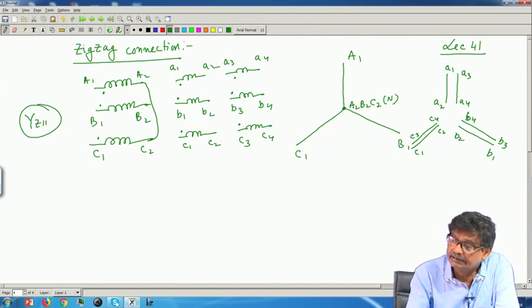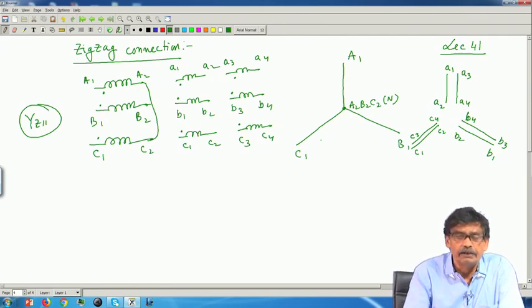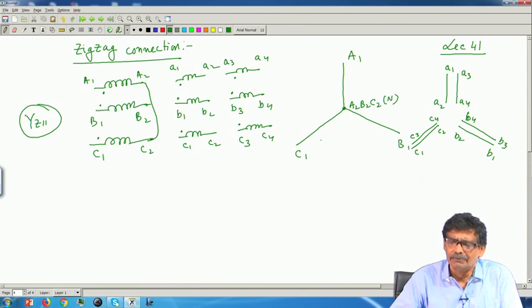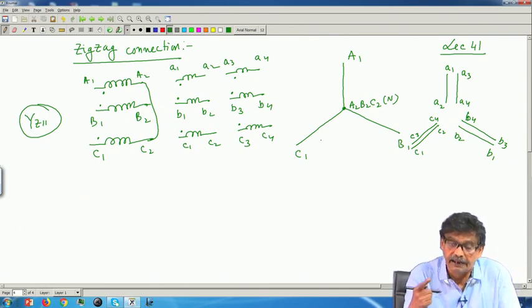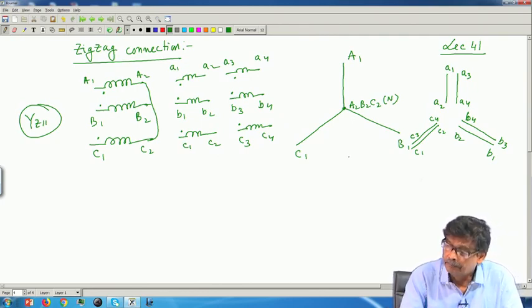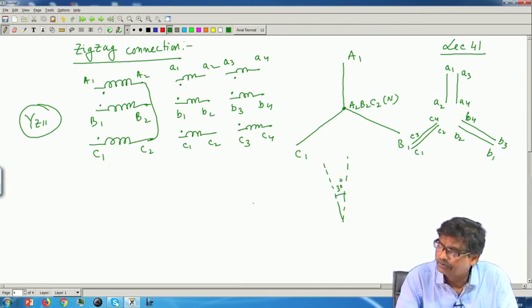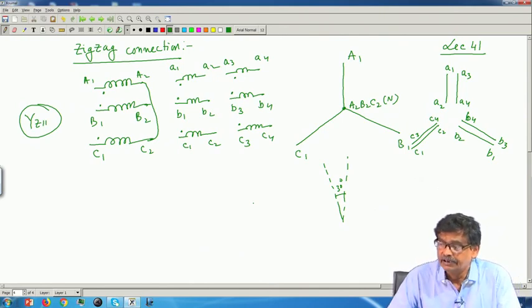Now, this is the primary voltage; whether 11 is possible. Zigzag connection, I know 3 terminals will be shorted. So, there will be a neutral point available, looks like a star connection. Therefore, whatever will be the phase voltage starting from that neutral of the secondary side, that A phase voltage must lead this A phase voltage. Therefore, I draw first this A phase voltage, that is at 12, and then I am expecting my phasor here at 30 degree. This is also straightforward, similar to the previous one. I am just doing this so that you get used to it.